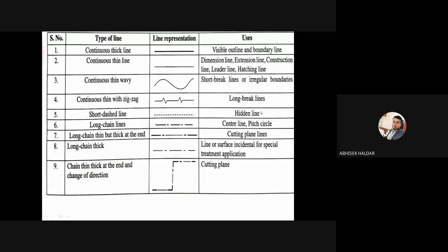When you discuss orthographic projection from assignment number 2, there will be some parts of the object that you may not see from your side, but some inner parts are there. Those parts are hidden inside the object. Whatever edges or parts are hidden, that you cannot see from your side, but are there inside the object, those hidden edges are denoted by this type of dashed line.